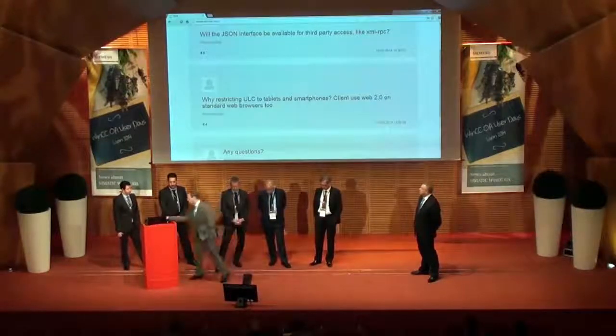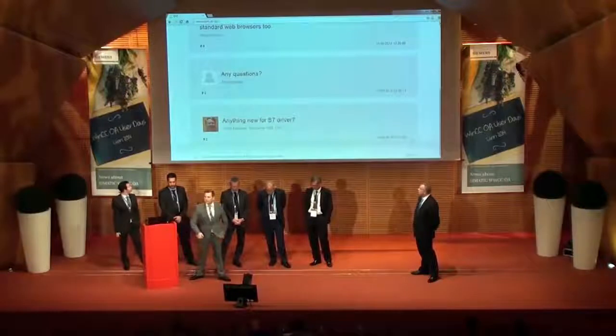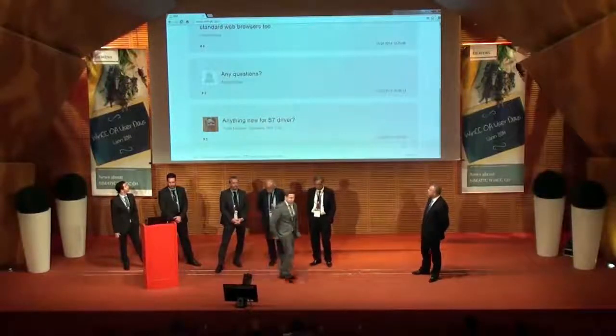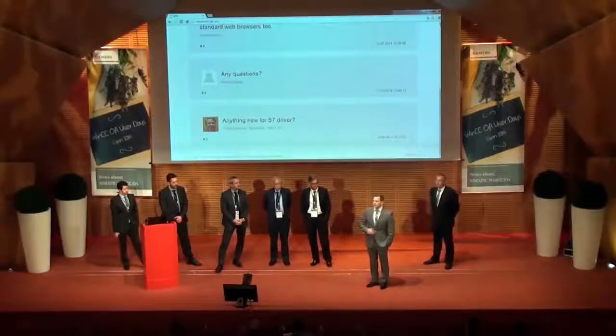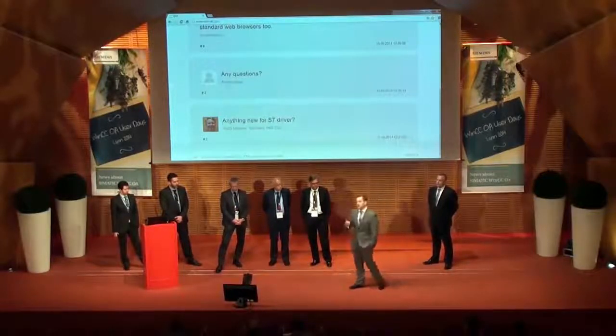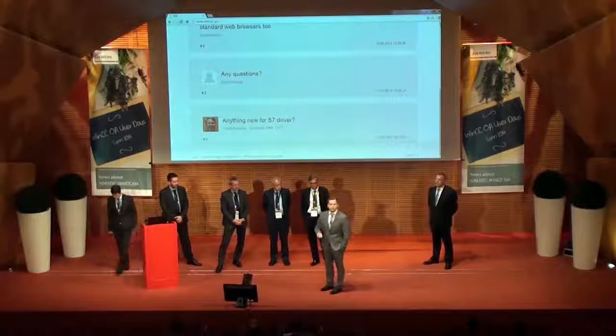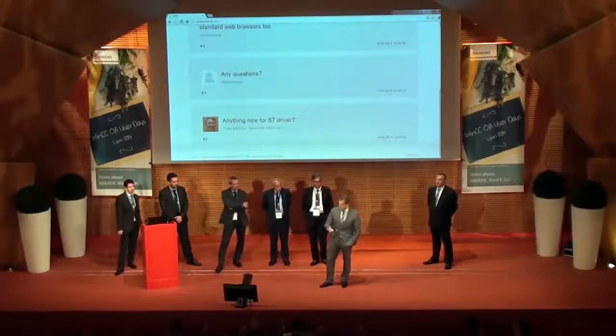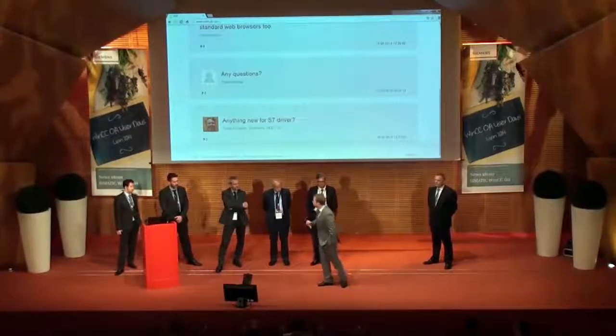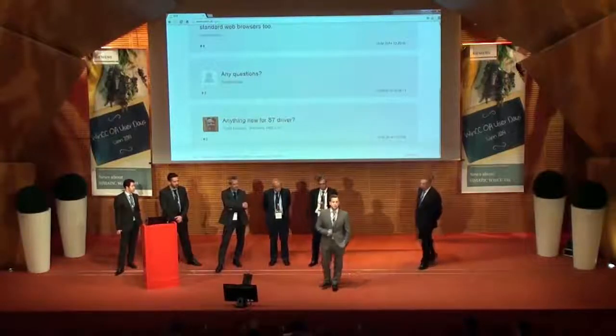There was one question from Todd about the S7 driver. Yes, our current S7 driver is able to connect to the S7 1200 and 1500, but not with the new symbolic addressing. It's working with the classic mode.